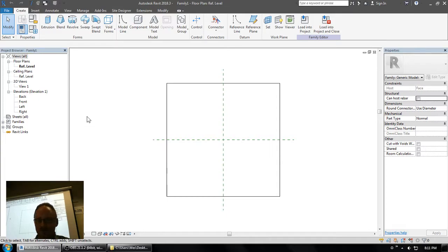All right, so, but yes? If you accidentally select the wrong family, can you change the host to a different face? Let's say you put the face-based family. Yep. And then can you change back into a wall-based family? No. So you are committing yourself when you're using these templates.